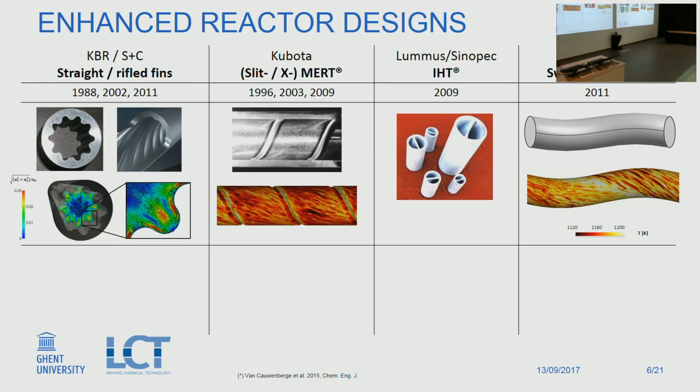The thing that you see on the simulation is temperature, from LES simulations. So you see just before the rib, the heat transfer coefficient is lower, so there your temperature increases, but behind the rib, the temperature is lower because your heat transfer is more efficient.